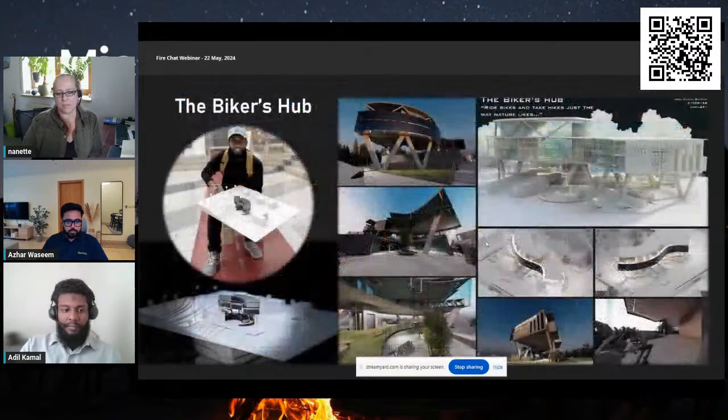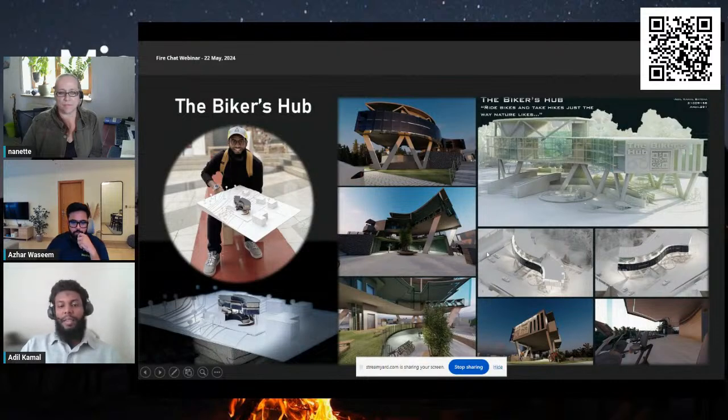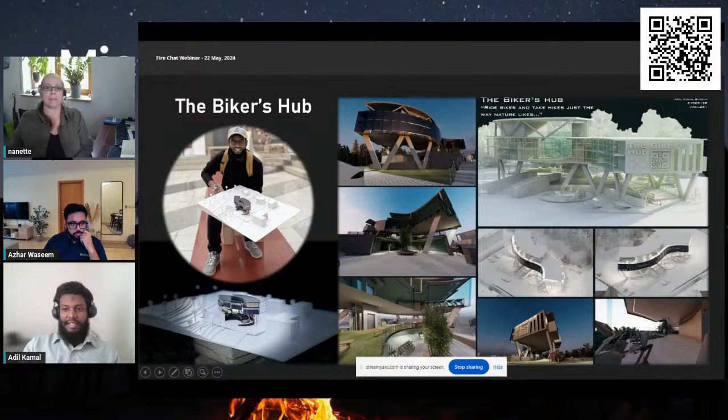Okay, before this, also in this project, we had a topography of 4.5 meters. One of the things commonly done is that when we have topography, usually people try to landfill it completely so that they do not really design topography. But for us, maybe you can even fail the design course because of such a thing, because topography is a great potential. In this case, how topography was used is that, the cursor, if you can see, this one is the entrance at 0 level, and then the site keeps going down to -3.